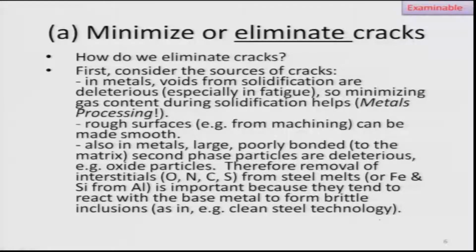First consider what are the sources of cracks. In metals there will be voids, like if you do solidification you can have deleterious effects like pores, because there will be gases, many other reasons for the pore formation in solidification. Or you can have also surfaces which are rough. Why? Because your machining can lead to rough surfaces, so that rough surfaces can trigger the crack. Also in metals you can have poorly bonded second phase particles.